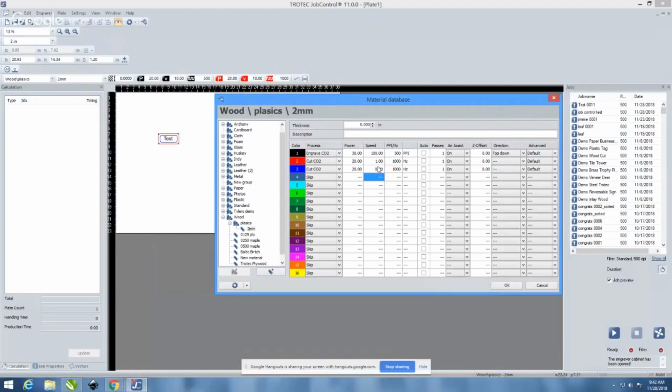So typically, to cut something really thin like a piece of paper, you might be at 4% speed, and 4% of 140 inches per second is still really moving quite fast. So the reason it's always a lower number is because it's a percentage of an extremely high number, being the engraving speed. For cutting through thicker materials, like maybe a 1/4 inch piece of wood, you'll often be less than 1.